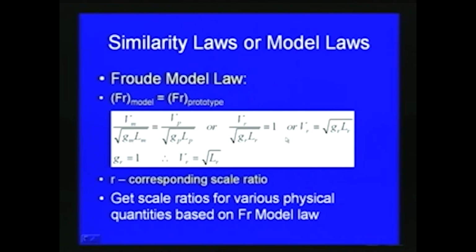In most cases, the prototype as well as the laboratory model will be under the same gravity, since unless we are going for centrifuge modeling with high gravity like 10 g or 50 g, in which case it is different.